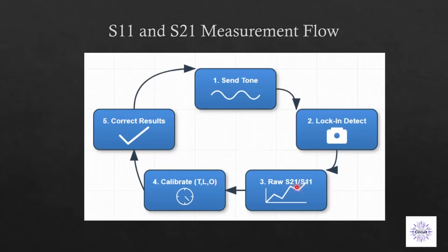One last thing is that if we want to measure S11 or S21, there are always inaccuracies because of the cables we have in the line, or if we have some attenuators or adapters, their mismatch or their loss may change my transfer function.